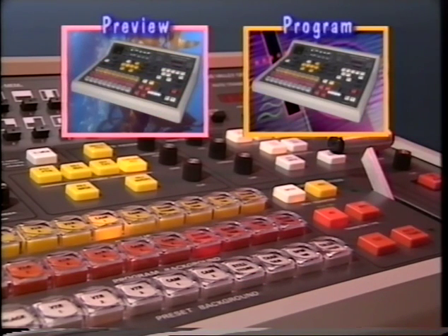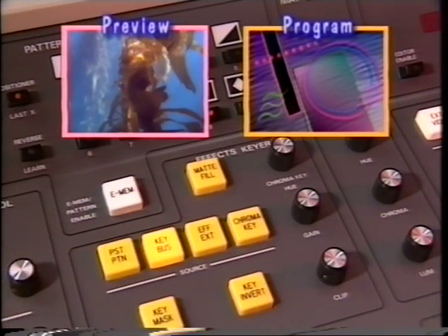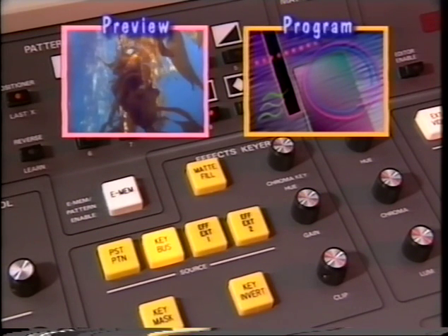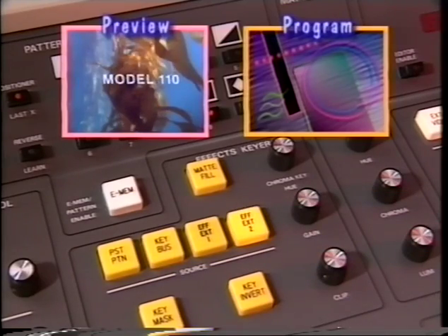When the chroma key option is not installed in the Model 110, an optional chroma key bypass board allows the chroma key blue input to be converted into a second effects external key source. With this option installed, the chroma key push button selects an external key input in the same manner as the effects external push button. New push button caps are provided to indicate the bypass board is installed.